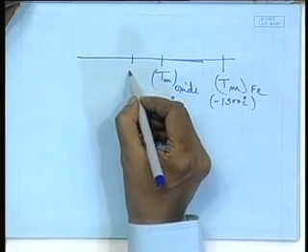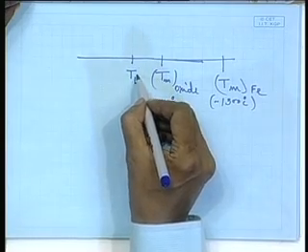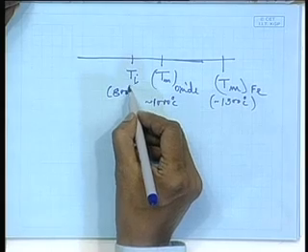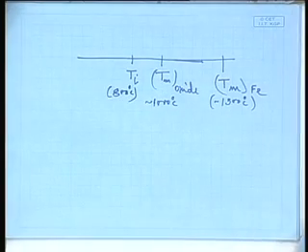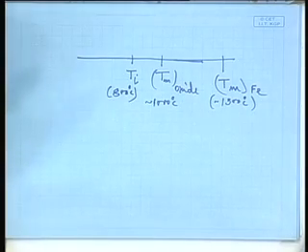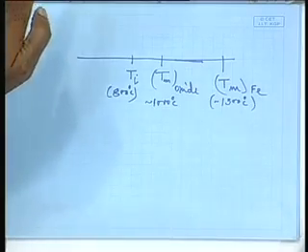Right. So, that is what it is. That means, when you heat up the material, and the ignition temperature is somewhere here around, well, ignition I write, that is around 800 degrees centigrade. By ignition I mean at the point where I am injecting more oxygen. So, when the plate attains that around 800 degrees centigrade, I press that lever to put more oxygen. How do I know that it has attained 800 degrees centigrade?